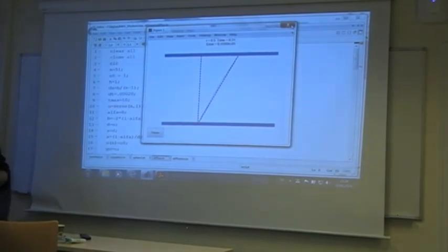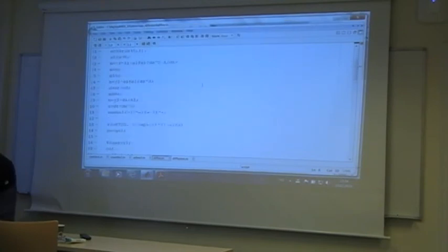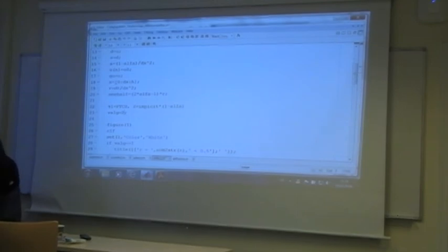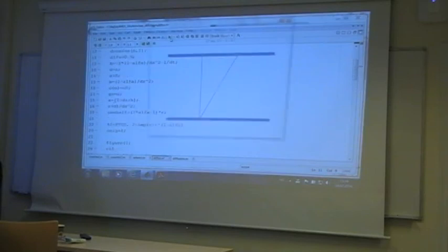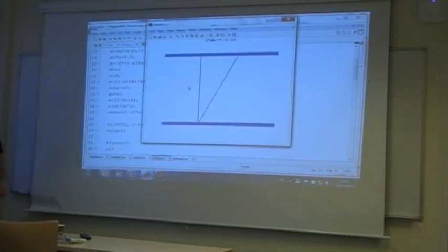And if you go a little bit above, it will explode. That was what we saw. But now I can choose a partly implicit scheme. If I choose number 2, and here I have an alpha set to be 0. Should have alpha equal 0.5. Then I take 50% of each. And now let's see what happens.